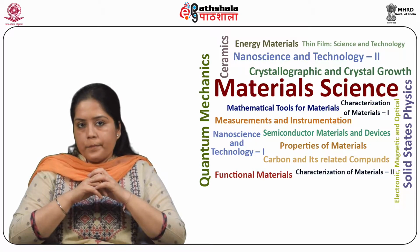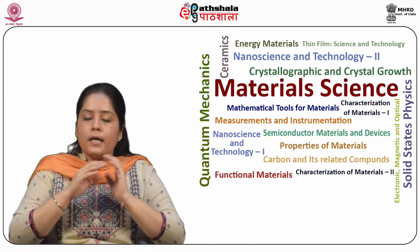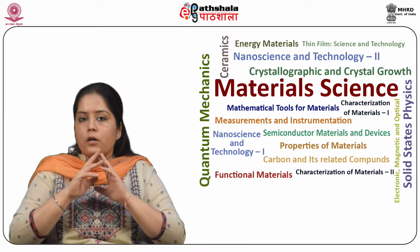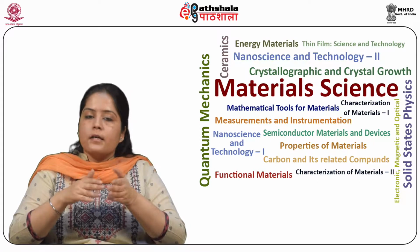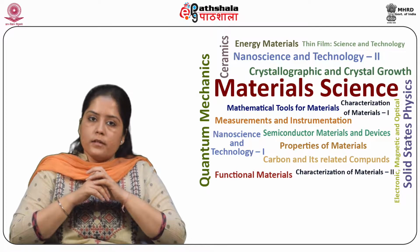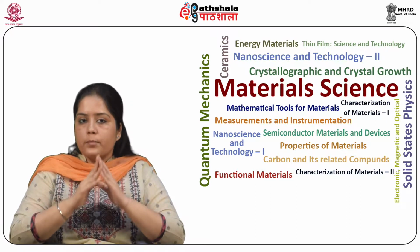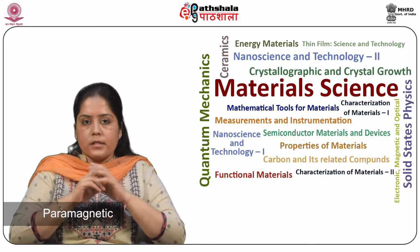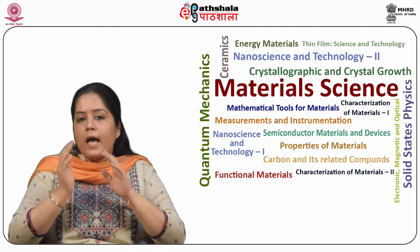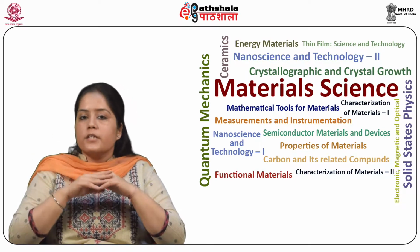Paramagnetic materials. Transition elements in the d group of elements as well as rare earths have incompletely filled orbitals and hence can exhibit very large net moment. As a result, the compounds consisting of these elements are typically strongly paramagnetic. All ferro, ferri, and antiferromagnetic materials are paramagnetic above their transition temperature.